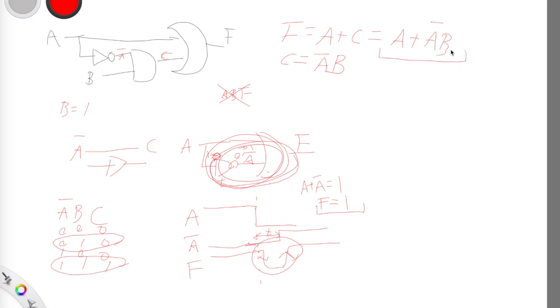Now you want to reduce the logic. How can you clean the logic? So if we want to reduce the logic, we want to reduce this term. And we need to make some new dependencies. So I would modify A to be A equals A plus AB. You know, it's still A. I can show you why.